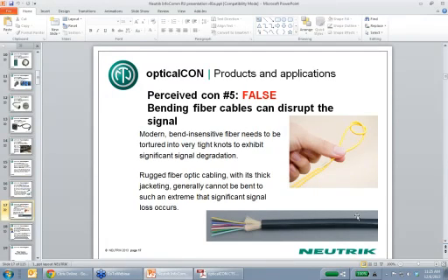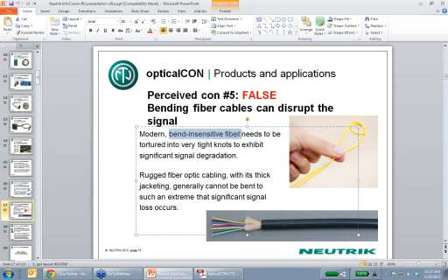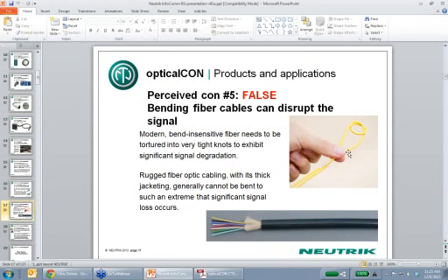All right, another con that is often discussed is that if you bend that fiber the wrong way, you can disrupt or stop the signal. This is old thinking. There's this new stuff called bend-insensitive fiber, which is really becoming more standard. The glass manufacturers are getting better at making glass which will resist attenuation when the fiber gets bent. So with the generic, non-rugged stuff, you can now tie this up in knots like this, and you generally don't have serious problems with the modern stuff.